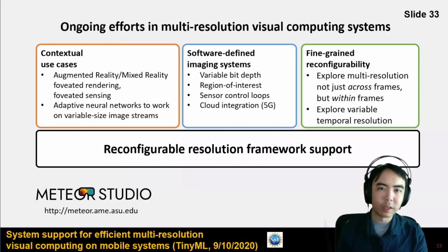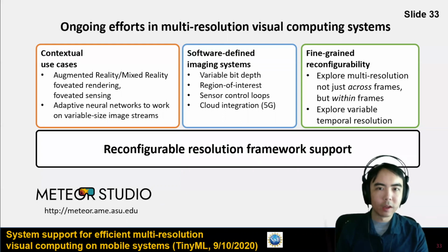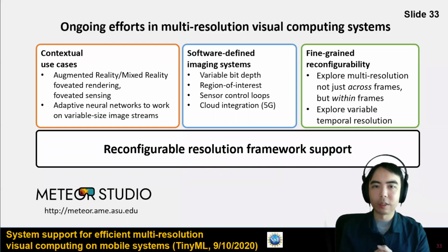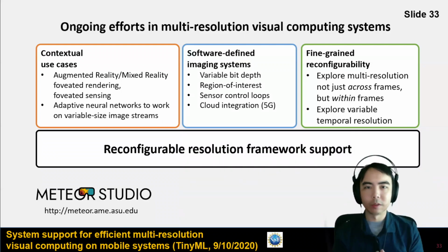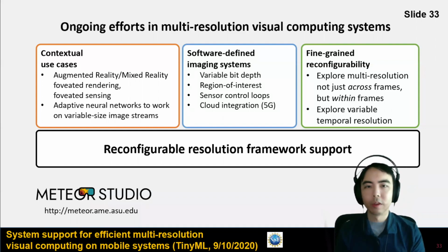But generally speaking, if you've got a high resolution sensor of whatever wavelengths you're filtering your pixels at, we're still able to apply the same principles. For example, set the sensor into different standby modes to save power, change the clock frequency to save power, and create these different media frameworks to process pixels through frame buffers without dropping any frames in between, and so forth. So I think a lot of these techniques are scalable to different wavelengths as well.